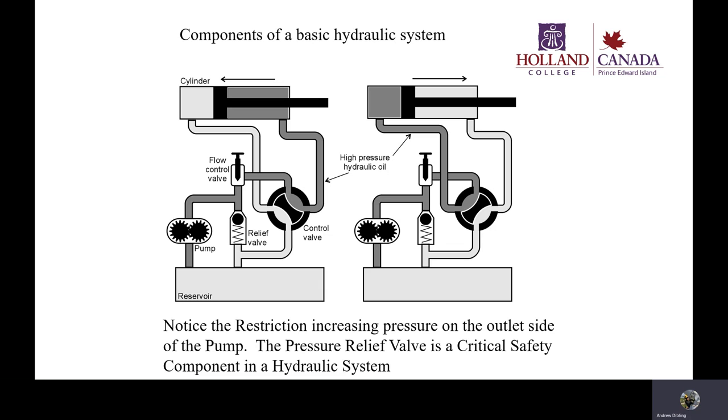A good place to look at the health of your fluid is the reservoir. It will tell you if you have water contamination, because water will settle out to the bottom because the hydraulic oil is lighter, has a lower specific gravity than the water. So as a result, the water will sink. Also, a lot of the precipitates will fall eventually.